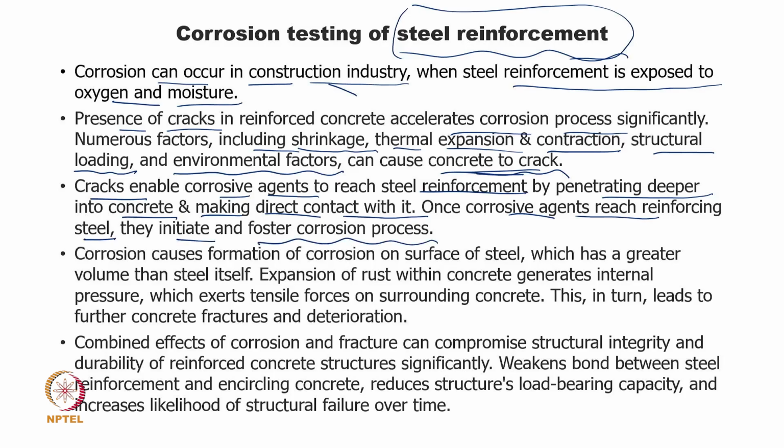So, this is well inside the surface, but concrete has a number of possibilities of cracks, and even with the naked eye we have seen on the surface of concrete that there are cracks, while we are talking about the very inside cracks, and they reach directly to the reinforced steel. And then once it reaches, naturally after that the electrochemical process is started, and then it will increase the corrosion rate. That is why in the earlier test we said that we want to know how the corrosion rate increases. So, in this case it can be shown that way.